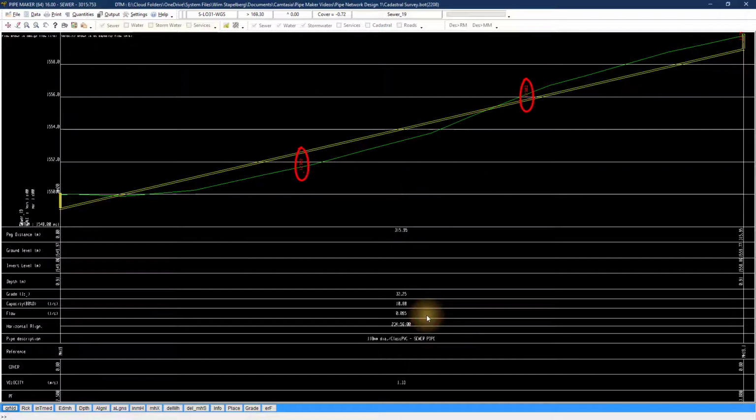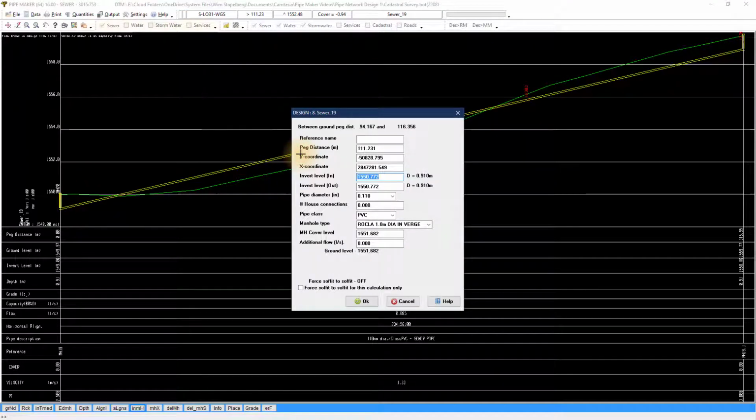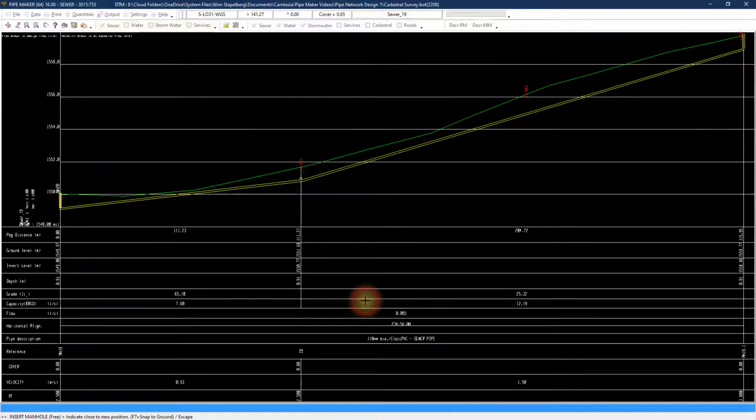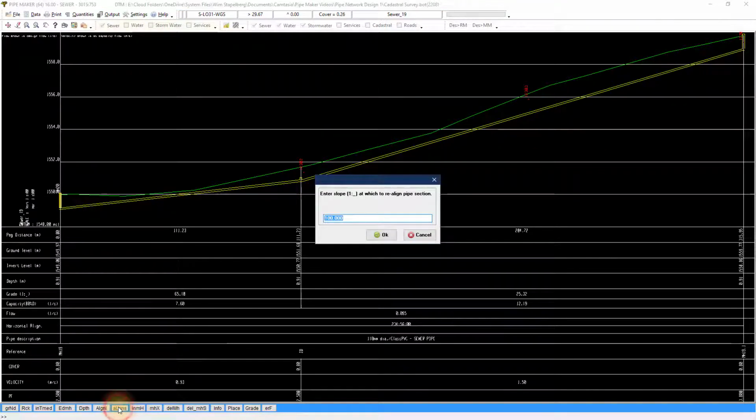Use the bottom menus to change the slopes and manhole depths so that the red warning messages at the bottom are white. I insert a manhole to drop the line lower between the existing manholes. If you make the manhole name JB, it will add a junction box. A line single will only grade a single segment. Select the inside of the segment close to the manhole you want to grade. All the earth connection points must be above the sewer line to drain.